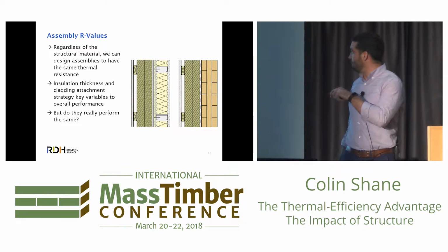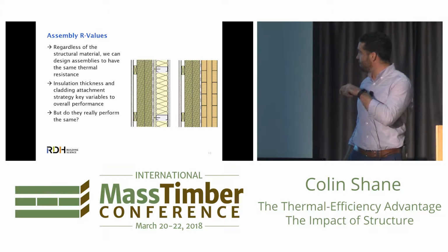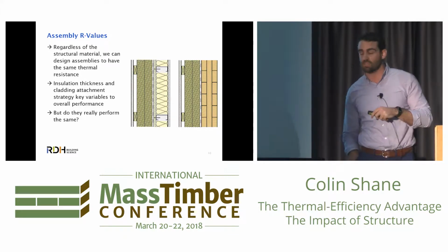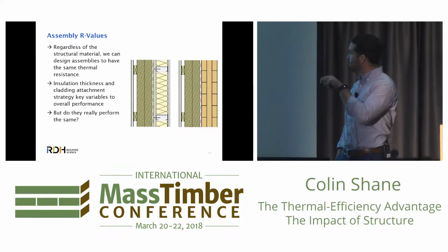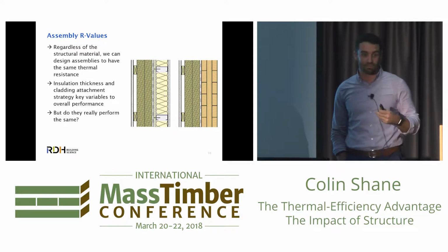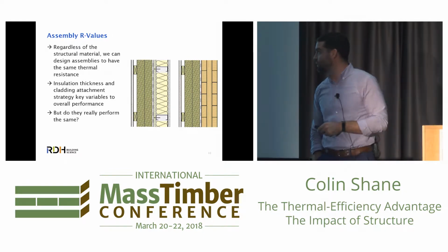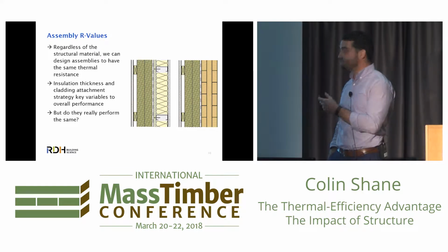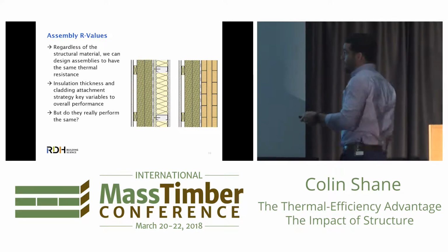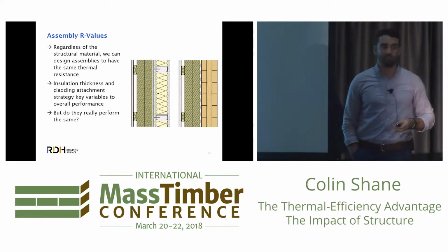Now, depending on how thick the studs are and how thick the interior insulation between the studs is, we may have to vary the insulation levels on the exterior to get these things to look the same from a thermal perspective in 2D. But we can do that, with pretty simple modeling tools. But do they really perform the same in real life?